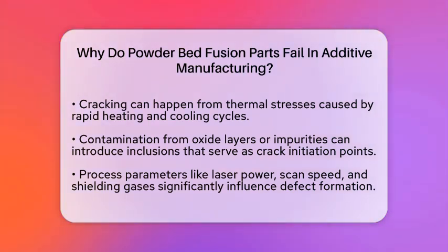Contamination is another factor. Oxide layers or impurities on powder particles can become trapped in the melt, creating inclusions that serve as crack initiation sites. Process parameters play a big role too. If laser power, scan speed, or hatch spacing are not set correctly, defects increase.